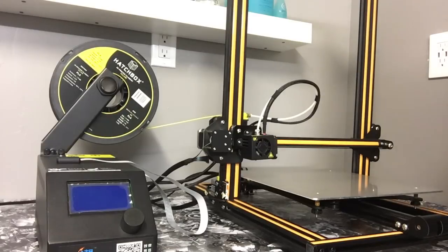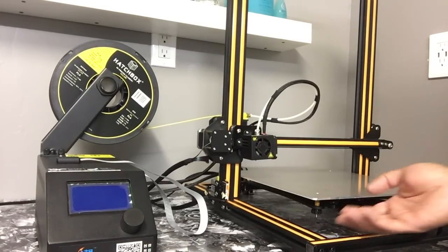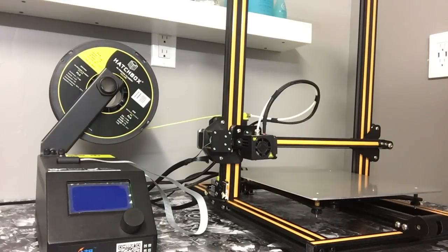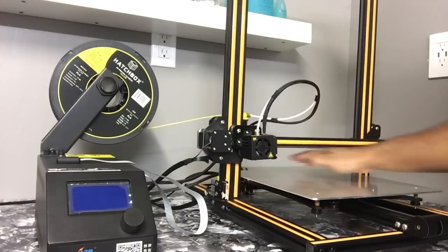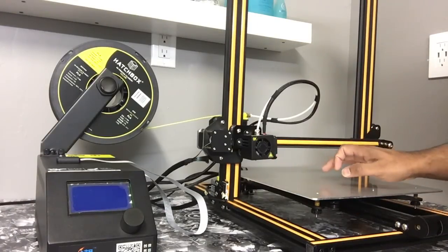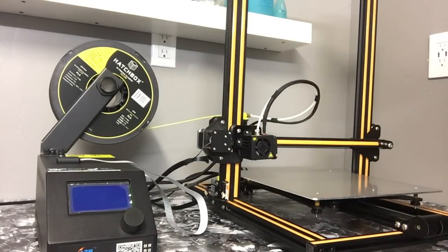Well, one of the main reasons probably would be that maybe you're just not adjusting these screws at the bottom right. I know people that do 16-point or 15-point tests, and that actually might throw you off. If you just do the four corners and the center, that will usually be good enough. Most people overthink bed leveling. You don't need to do that. Just take your time, do it once, measure twice if you have to, and just do it the right way, and you should be okay with that.